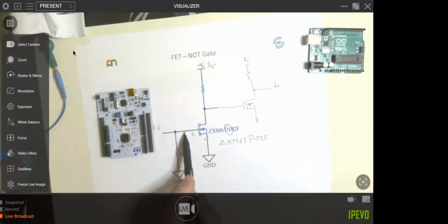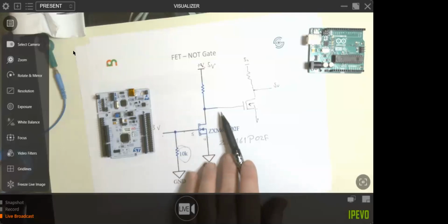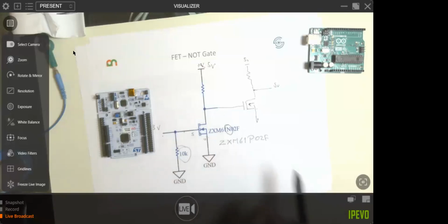It's just not a good place to be. You want to definitely know what you're doing. So if it's floating, say during reset, or if it's just unprogrammed, like when you buy a chip, a pull down resistor or pull up, doesn't matter which, depends on your circuit, is a good way to be sure that your output is always going to be at a known state. Top tip.